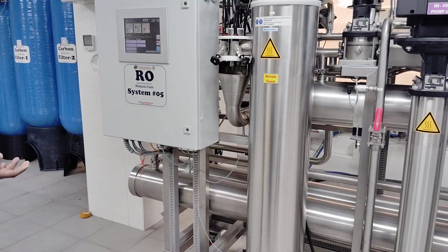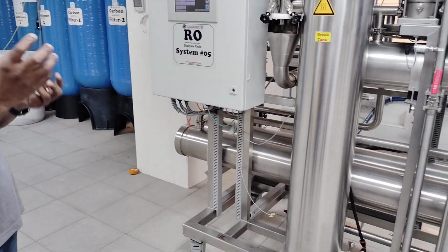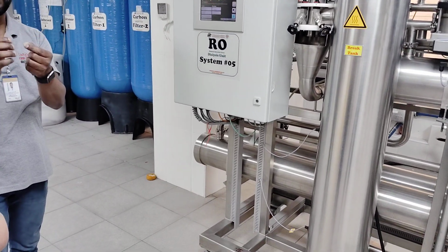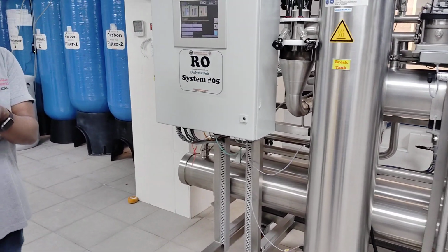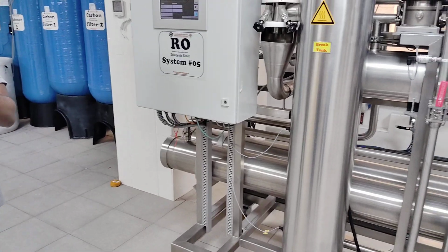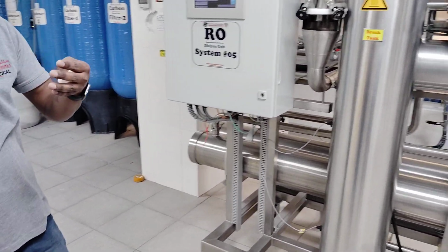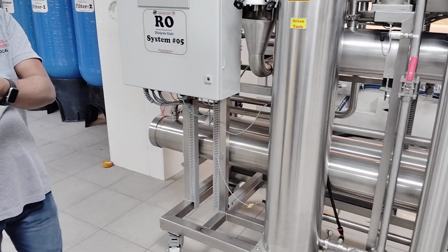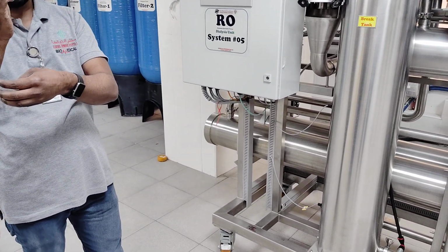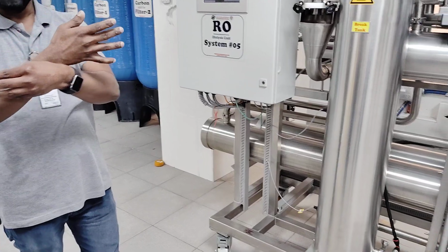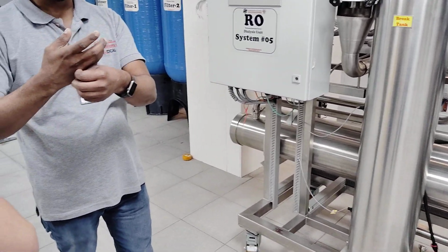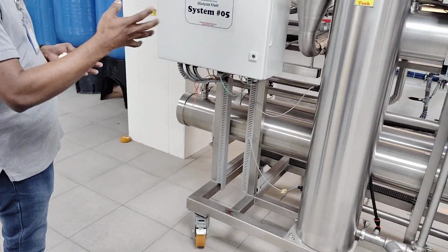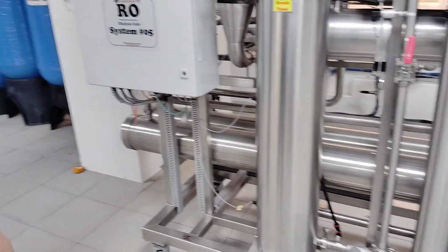So what that membrane is trying to do is, there are many very small filters, fibers inside, with point-something micron size. When the pump is running, it's high pressure and it pushes the water through that membrane. There are small holes, pores, you can't see them, very small. Through that the water passes, trapping all the endotoxin and bacteria and holding them there. After that the water coming out will be clean water.